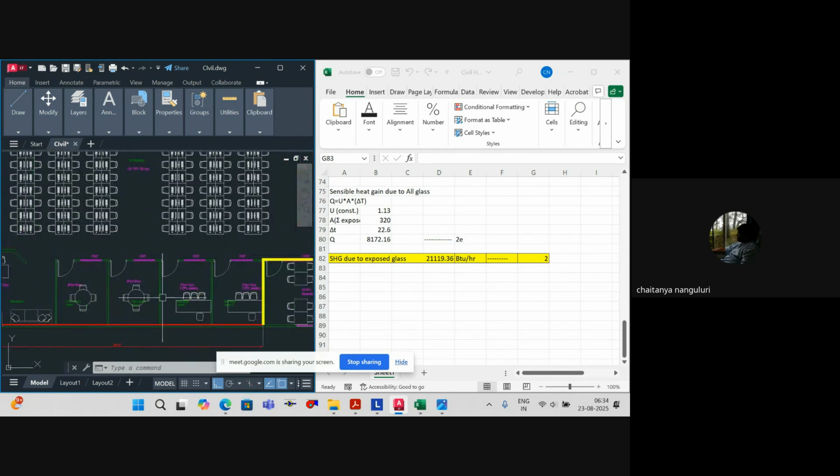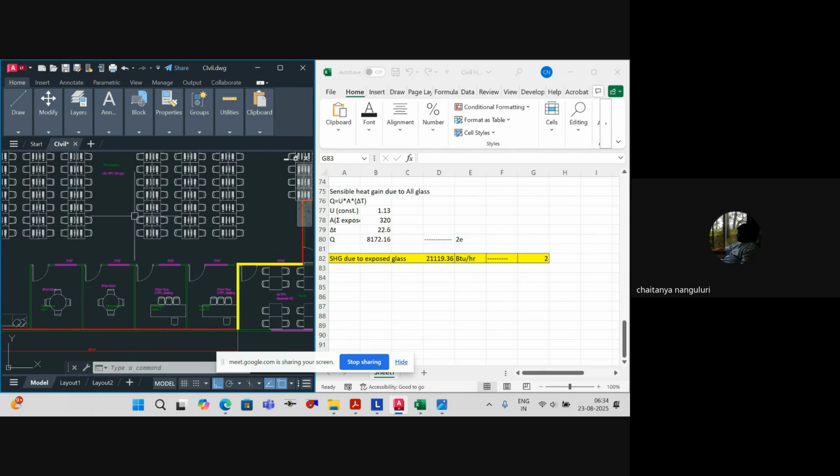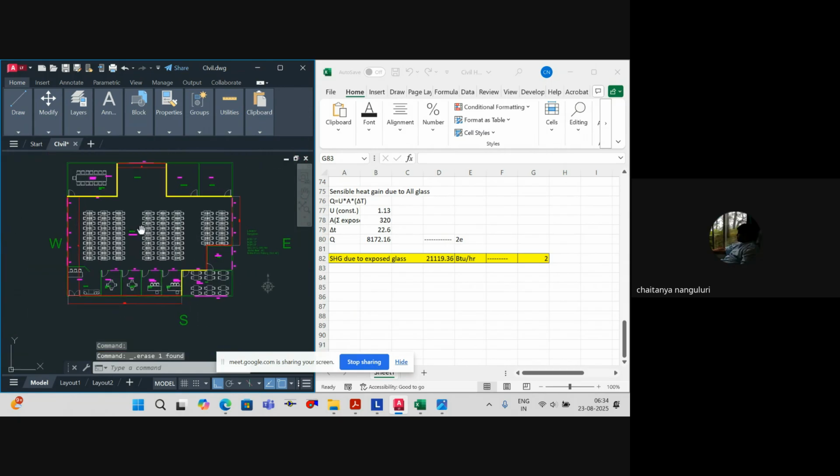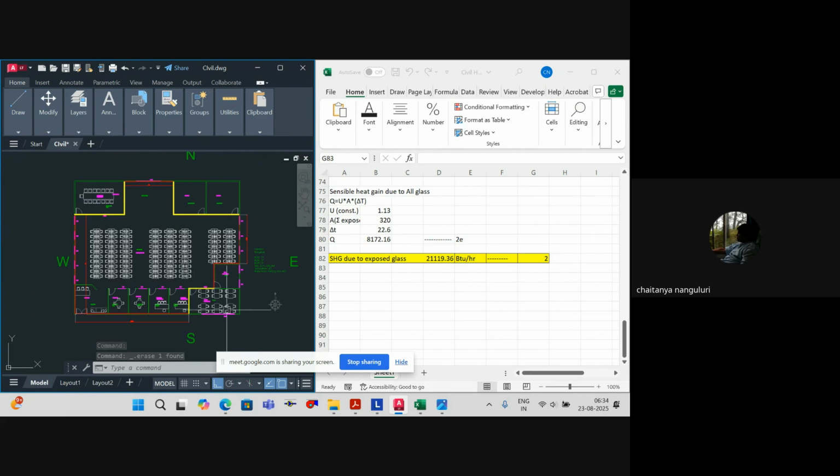These cabin walls, are they partition walls or not? So I have to take these walls as well? Come on, it's a part of our air conditioned space only. So why will an internal wall be a partition wall? I don't have a separate AC for the cabins, right? It's a centralized air conditioning system. So considering these things, only these are the total partition walls.